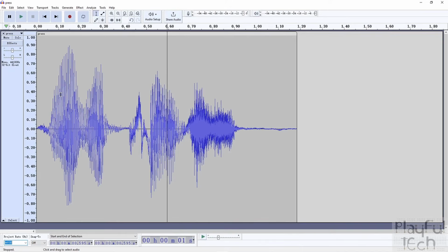So a completely empty chip, and then you can either save files to it individually in the order in which you want to index them, or you can prepare all your audio files in a directory somewhere on your computer using sequential numbers, and then drag them over all at once, and your operating system will, generally speaking, take care of the fact that they'll be copied over in the correct order. That's going to give you predictable index numbers so that you can call the correct sound effects from code or from the appropriate trigger pin.